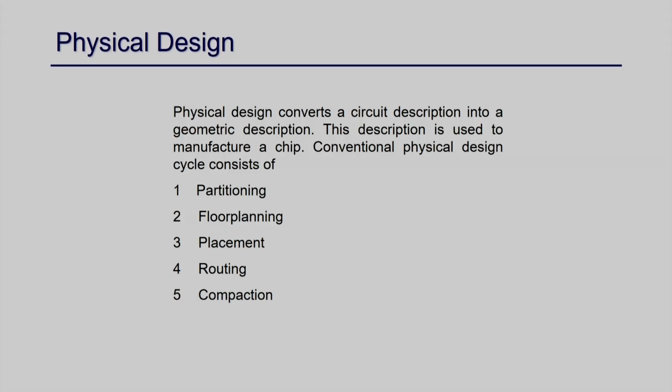Once this is done, we will go for fabrication. You also remember that at this point the gate level design will be converted to a transistor level circuit, which is a very obvious transformation, because it is just a replacement with the equivalent circuit representation of each gate. So, that is not a big task of physical synthesis. We can easily convert gates to the transistor level circuit, but what is important here is making a physical placement of those gates and then making physical interconnections, right. So, let us go into these physical design steps.